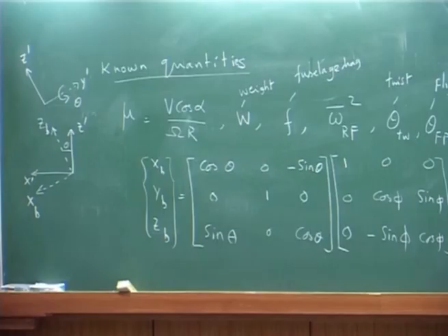If you have a heading, that also will come. So these angles are basically with respect to the Earth coordinate system? Not exactly, these are Euler angles, do not say Earth coordinate system. Again, I wanted to ask you, what do you get from the gyros? Gyro will give you rate, okay, that I will come to later. Gyro will give you angular velocity. Angular velocity is a vector, because instantaneous angular velocity it will give you about 3 axes. If you have a 3 axis gyro, you will get rotation about the 3 axes.